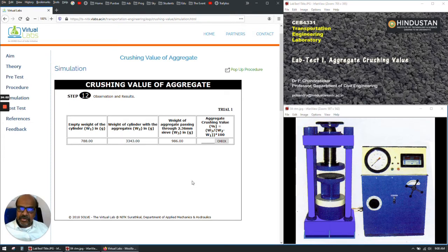It's a percentage of the powdered form to the original form. If that is lower, very good. If that's very high, that means too much powder, too much dust, too much breaking there. That's not good. You can calculate this and enter here. That's the proper way to do it. Well, I accidentally found out that if you click 3 times, it gives you the value there. Don't be lazy, just do the calculation and put it there.